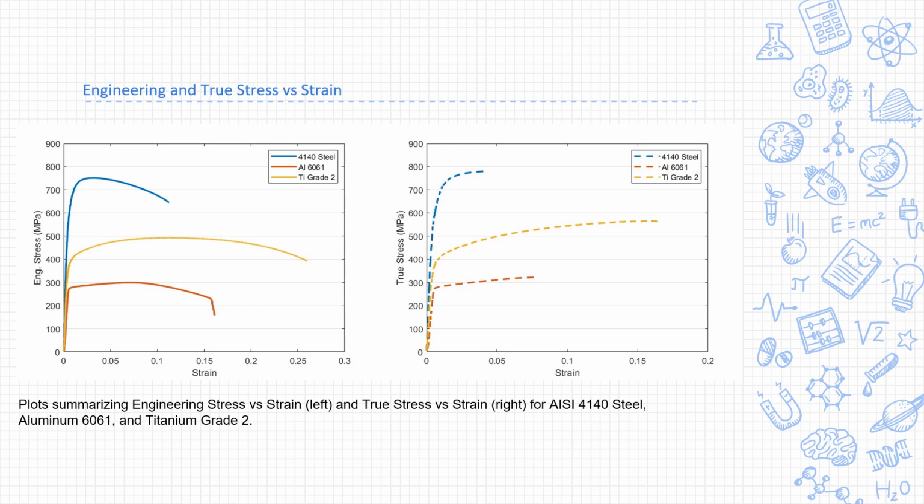As you can see, the stress curves do not follow the extent of strain as the engineering curves on the left. As deformation is a constant volume process, we can reach a point where dramatic necking occurs. At this point, the stress state is no longer uniaxial, and the assumptions we make around uniform plasticity and material flow no longer apply. This occurs around or after the ultimate tensile strength is reached, which we can see correlates with the degree of strain the stress curves end.